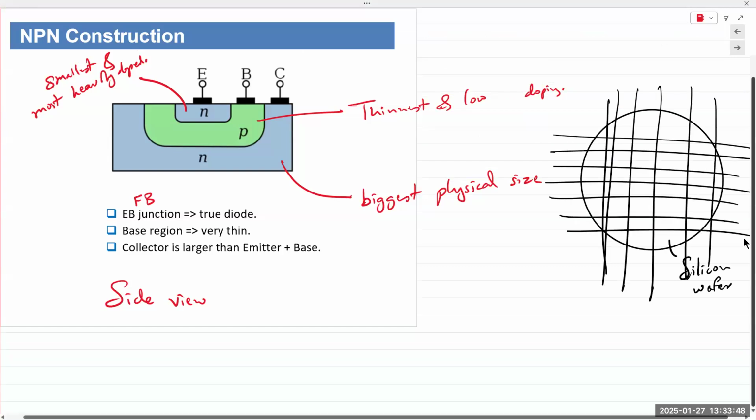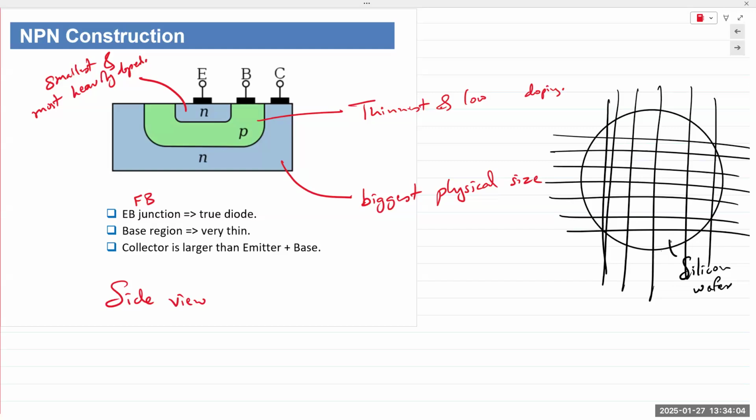An entire silicon wafer. This is, let's say, a typical academic wafer would be about 4 inches in diameter. Production wafers or facilities are typically 8 inches or 12 inches in diameter. So big circle, flat circle. The thickness is typically about 500 microns.